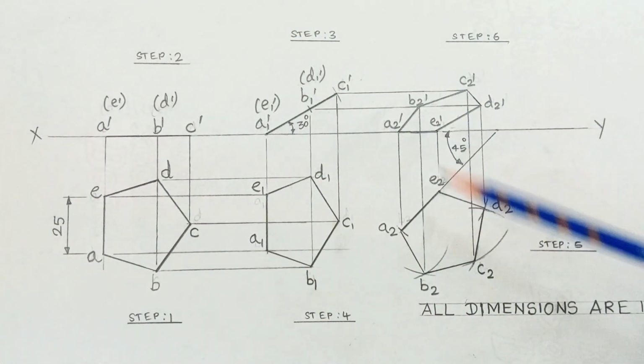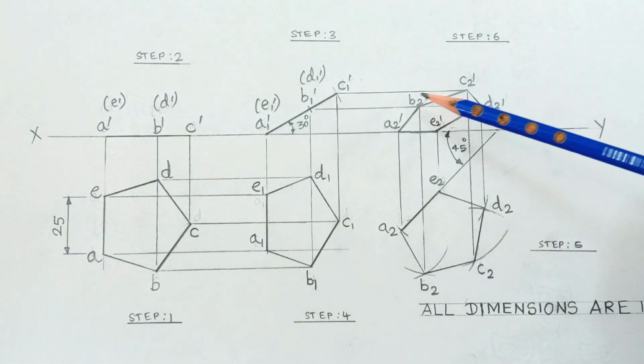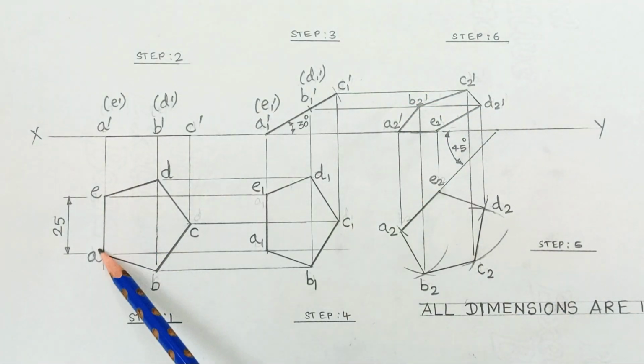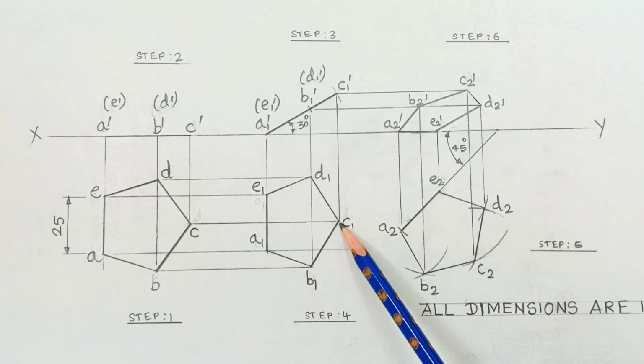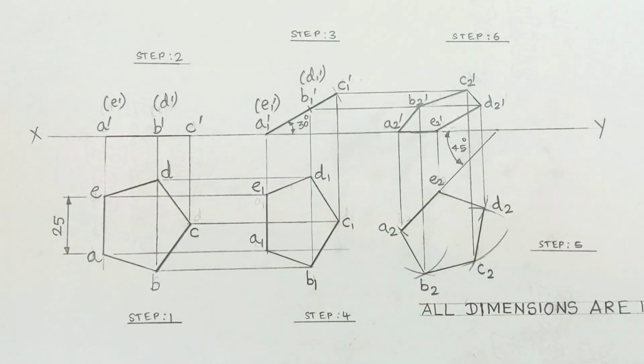And moreover, these vertical lines, these horizontal lines are called projection lines drawn by using 2H pencils. And this object line is drawn by using H or HB pencil, appears to be dark. Okay. So this is how the drawing appears when drawn on the drawing sheet using a mini drafter.